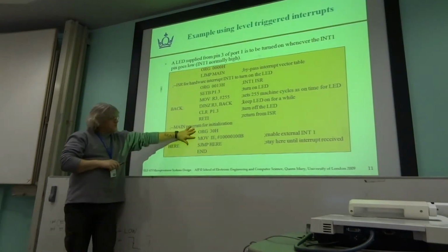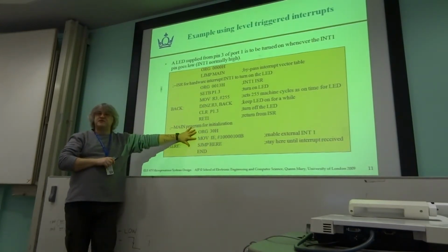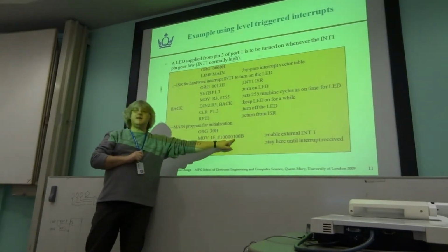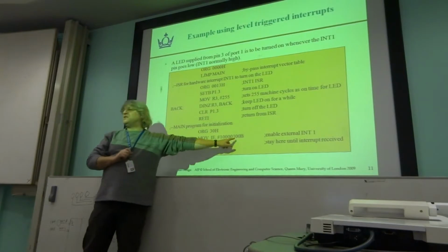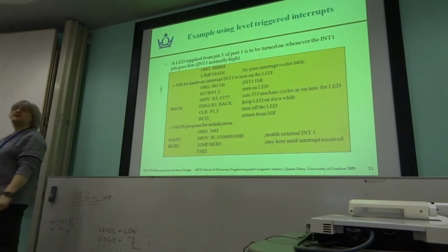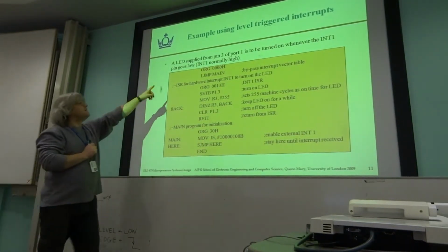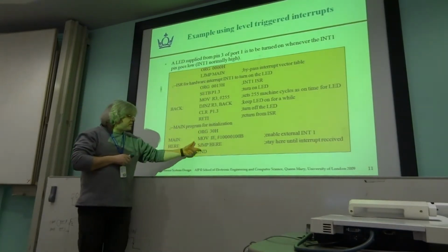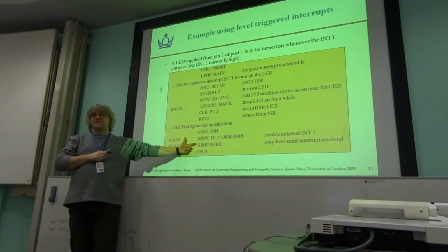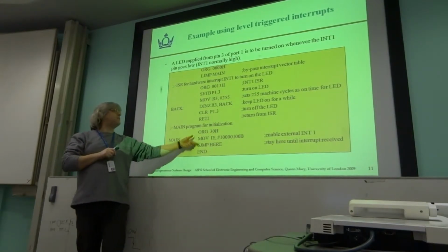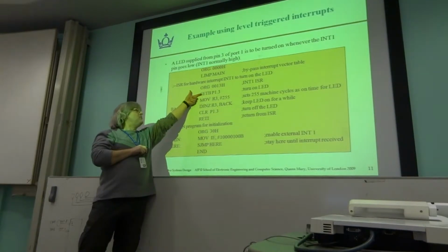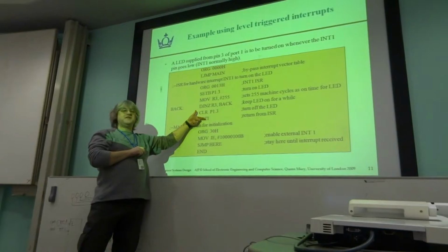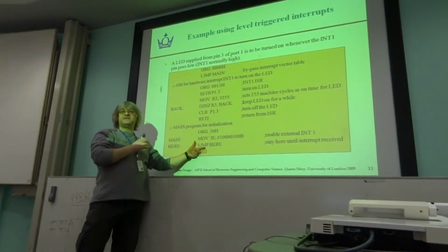And here we've decided which interrupt we're going to switch on. 2 bits have been set, the global interrupt enable, and this bit, which switches on external interrupts associated with interrupt 1. And then the main program just sits here doing nothing. So every time you press the button, the interrupt happens, turns the LED on, counts for a little bit of time, turns the LED off, finishes the interrupt routine, and waits here again. Does that forever.